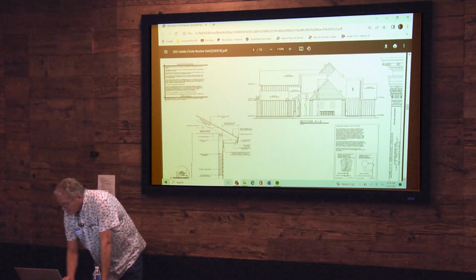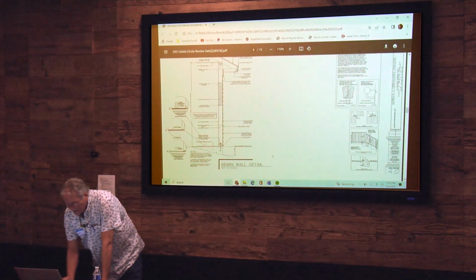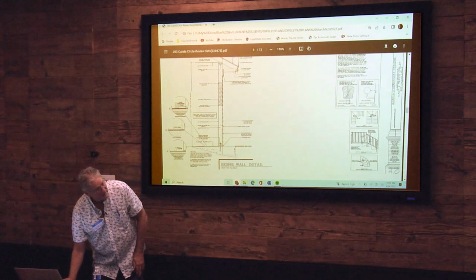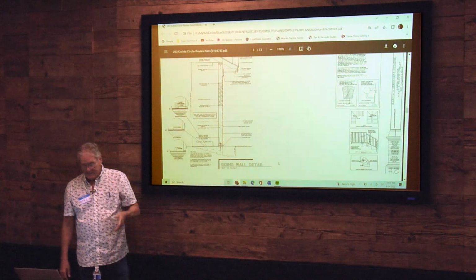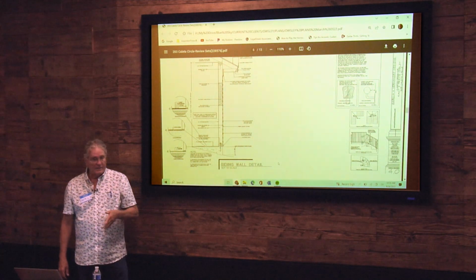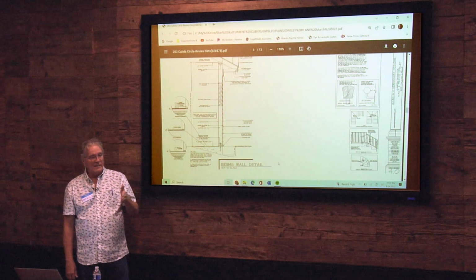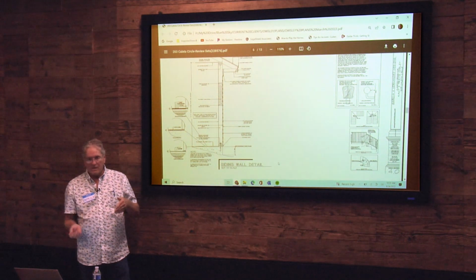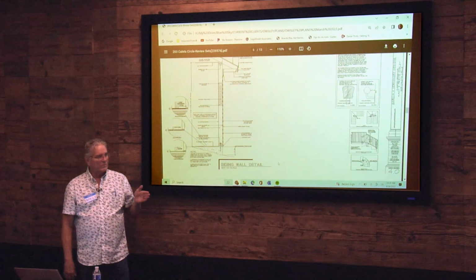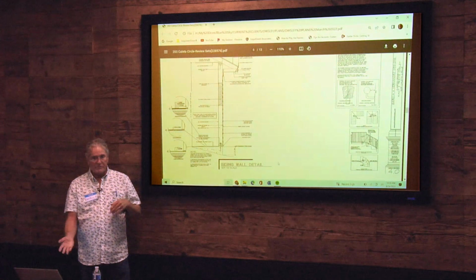So just be clear that when it shows us a wall section, this guy just says siding wall detail. Again, can you see my cursor moving on that? Okay. Just says siding wall detail. Again, it doesn't say typical, it doesn't say specific. The assumption process here, you would assume, gosh, maybe it applies to the house because there's board and batten siding all over the house. But then when you look at the soffit overhang, it doesn't conform to what's shown on the house. So then the question comes up, is this detailed or specific?